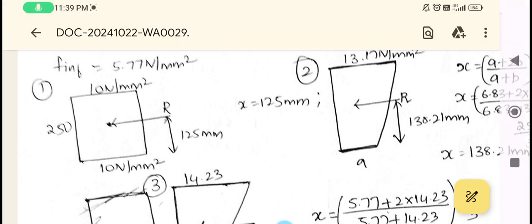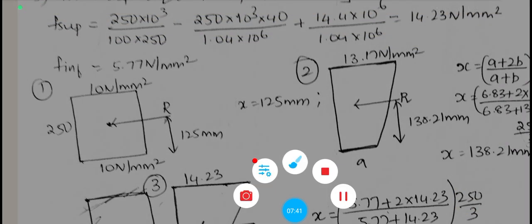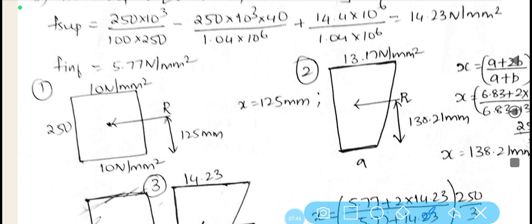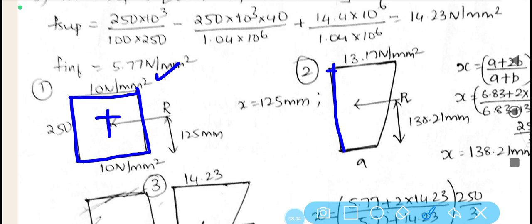Okay, next, let us plot the stress block, that is the stress distribution profile. We know that the stress due to the pre-stress, the direct stress, is always compressive in nature. Therefore here the stress block which has been obtained as positive is the direct stress due to the pre-stress. And second case, draw a vertical line. We have got f superior as 13.17, f inferior as some value which we have received from the expression, and connect both.